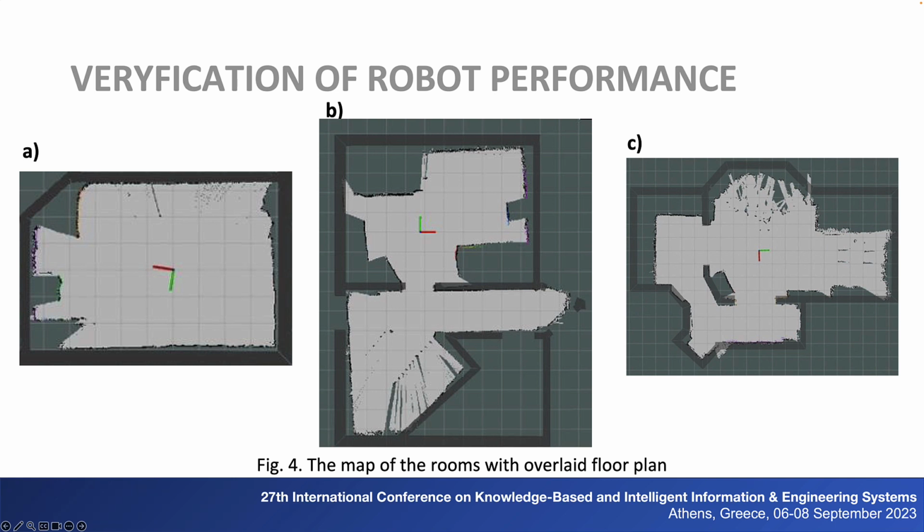After performing the test and analyzing the resulting map, two problems were noted. The first is the distorted distance measurements, particularly evident in the bottom left-hand and the upper right-hand corners of the map due to poor illumination of these areas, which affected the quality of the measurements received from the sensor. The second problem is the curvature of the walls resulting from the increasing error in distance measurements from the encoders. The error was mainly influenced by surface irregularities and slippage between the wheels and the driving surface.